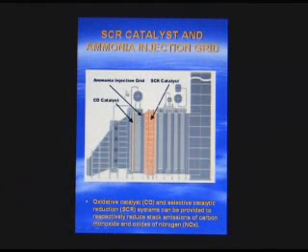Example of the catalyst: you have your ammonia grid, your CO catalyst, the ammonia grid for NOx and CO reduction. And we have another catalyst back here. Pardon me. The ammonia grid is used to augment the SCR catalyst to promote the conversion of the NOx to reduce the NOx levels.